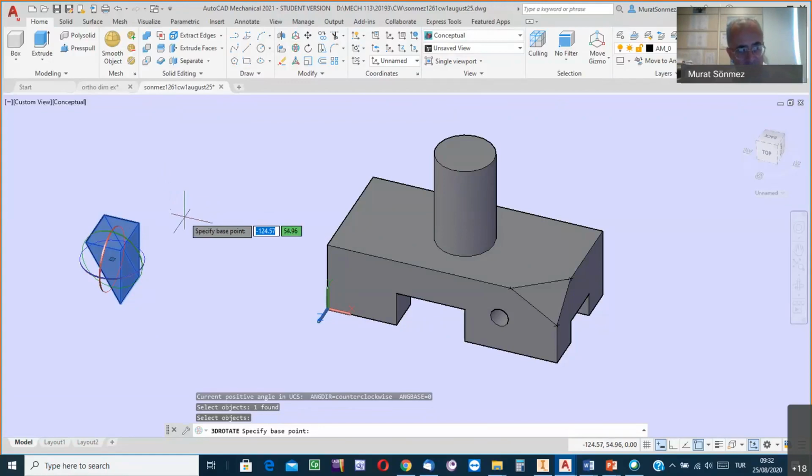There is a simulation. In the simulation, there are 3 circles. One of the rings is red. It implies that it is the ring to rotate the body about the x-axis. You know, for the x-axis, AutoCAD uses red color. The other ring is green. This means if we indicate this ring with a click, then we can rotate the selected object about the y-axis. And the third one is blue. This means it is for rotating the prism about the z-axis.